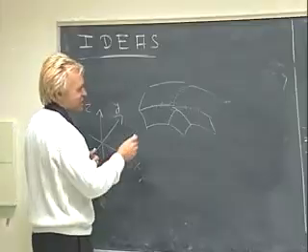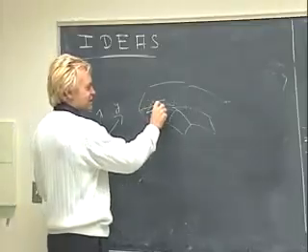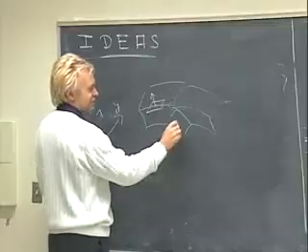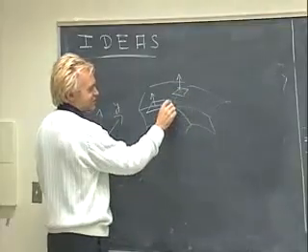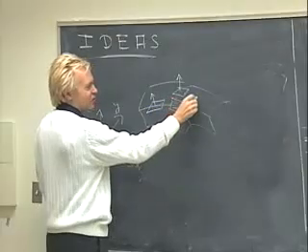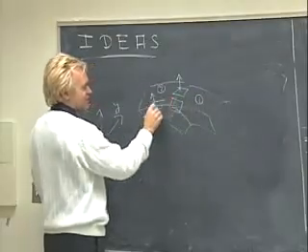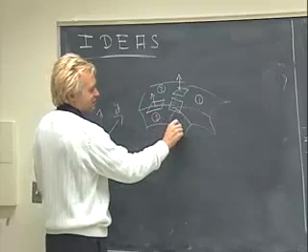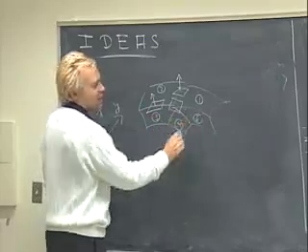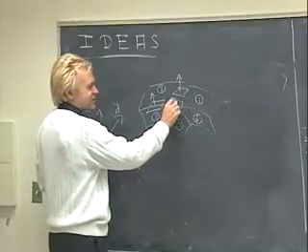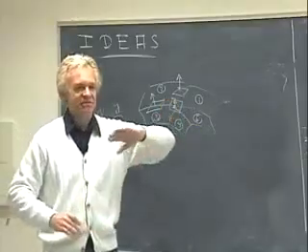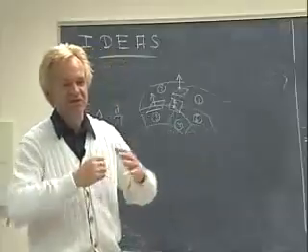So you have to worry about the same normal everywhere at these shared boundary curves, but you also have to worry about the same normal for all 5 patches. Right? So there are 5. 1, 2, 3, 4, and here is 5. It goes around, and at the center vertex here, you also have to make sure that there is the same tangent plane, the same gradient, the same slope for all 5 patches when they come together.